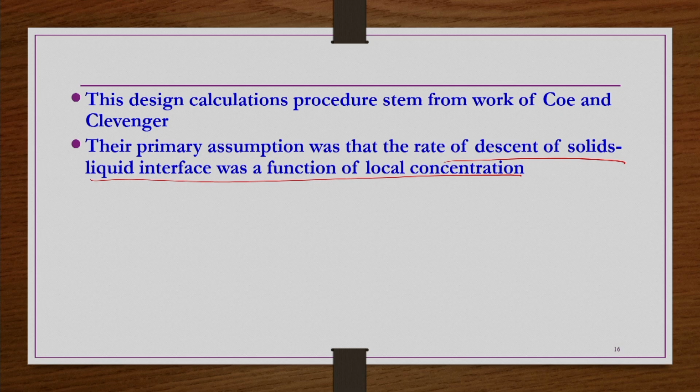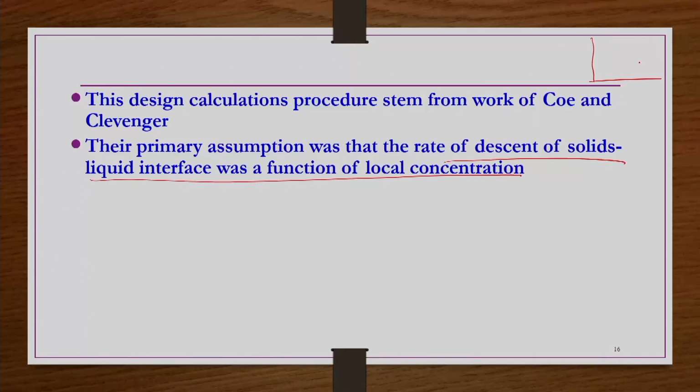We have seen the settling velocity curve, that the interface height gradually decreases. This is what we have seen, Z versus t, one of the pictures we have seen. In the initial times it decreases very rapidly like this. That means initially the concentration is the slurry concentration whatever was there, and then gradually the concentration towards the other side is increasing.